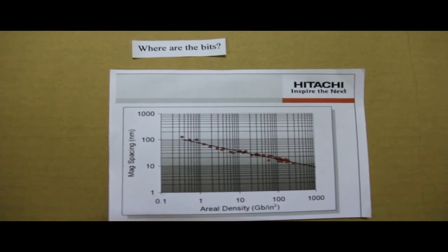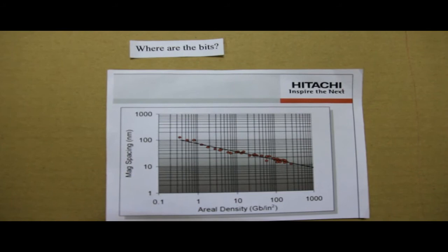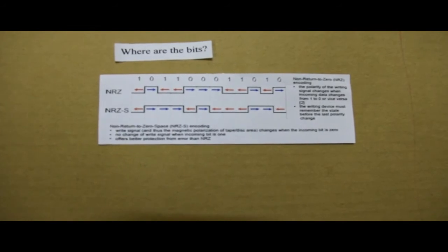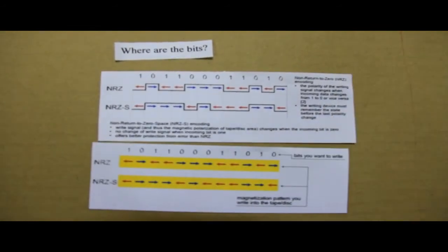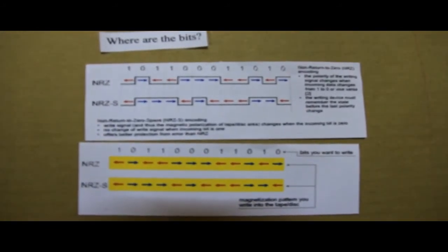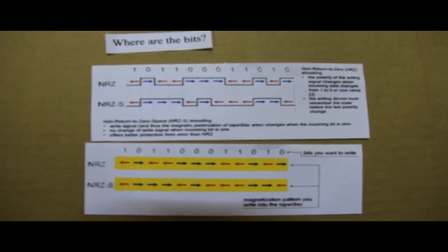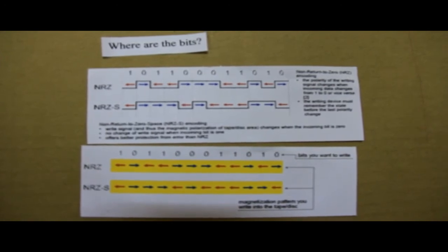Due to the strong dependence of the stray field strength on the vertical distance from the medium, the gap between the reading head and the tape or disc must decrease with increasing bit density. In electronics, in the presence of external disturbances, noise, registering the change of a voltage is faster than determining its value. Consequently, the bits are read not as a value of the magnetic field associated with a magnetized region but as its change.